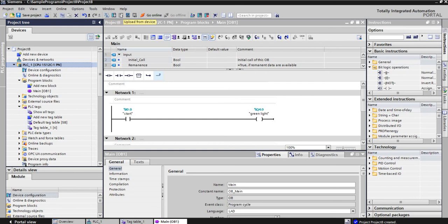All right, we can upload from the device. So that means if there's a program already on the PLC that you want to use or save, you can upload it and store it and save it somewhere else. What you'll do later on is make a few changes, and then you can just re-download the block. But on the initial download, we want to compile everything and then download the whole PLC versus the block. Sometimes you can screw some things up if you just do the block and you don't have all the correct matching CPUs and everything on the PLC.